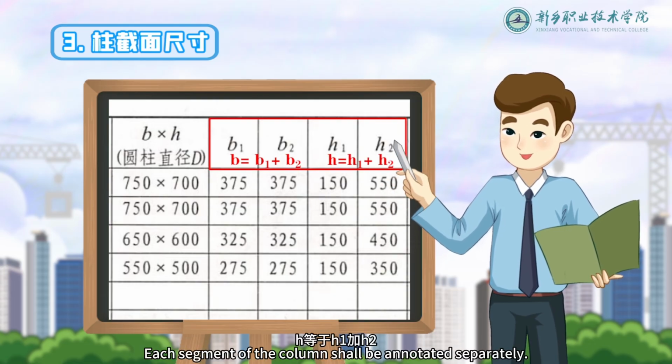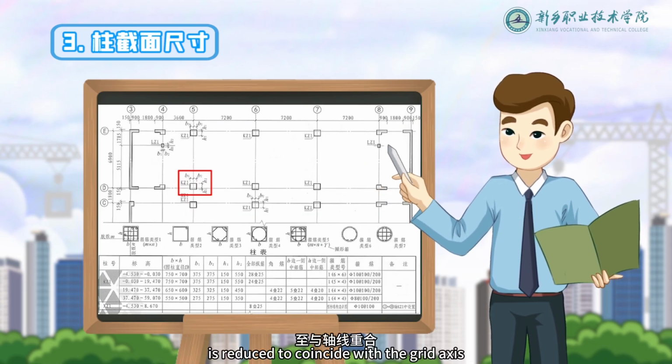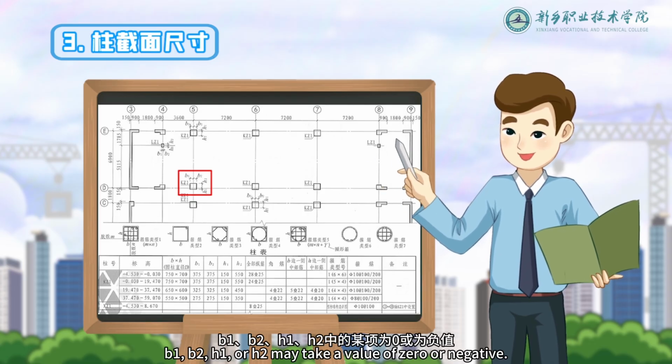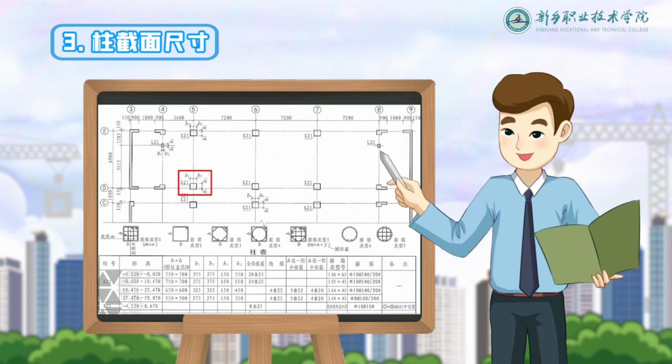Each segment of the column shall be annotated separately. When one side of the cross-section is reduced to coincide with the grid axis or shifts across the grid axis to the opposite side, b1, b2, h1, or h2 may take a value of 0 or negative.